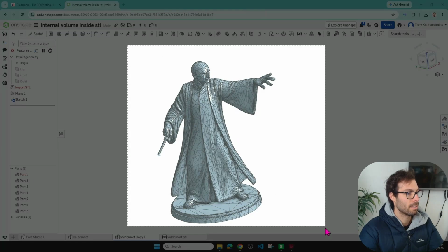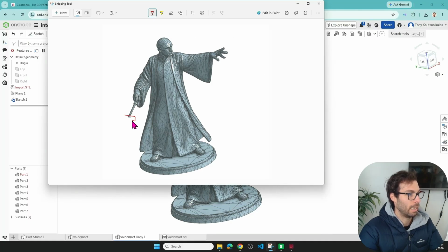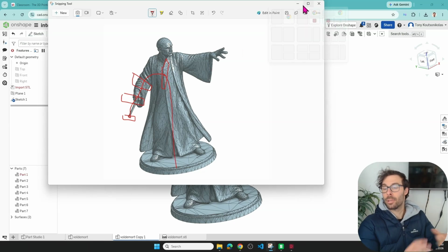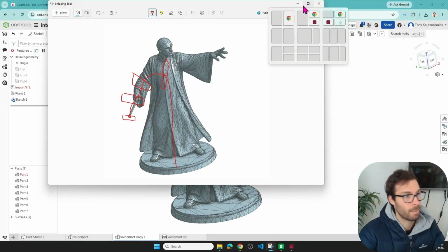To achieve this, we've created a plane here with a circle, and that has a point on it. And I can create a series of these along the path that it needs to take, just with dots on them, right? Maybe I've got another one that goes into the page like this, right? And that will allow me to create a swept curve that will go through the part. And then when I 3D print it, that curve can be a negative volume. That's what I'll be doing.